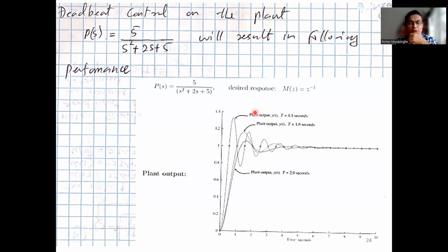All right. One more thing I want to tell you about deadbeat is that if you want to have any control system which is minimum time, I think the answer is deadbeat control. This is the control system which gives you the fastest response. It doesn't mean it's optimal, but it's minimum time. If you want to get something done in minimum time, this is one approach. If you want to go this way, you throttle maximum. And if you want to go the other way, throttle maximum on the other side. We can understand that, the principle.